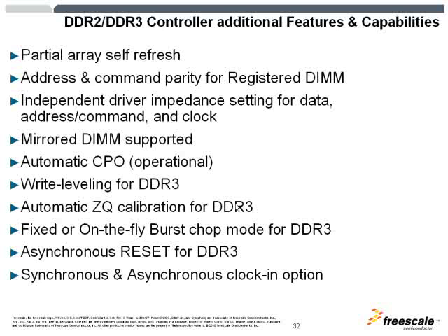Fixed or on-the-fly burst chop modes for DDR3 are available. We touched on this briefly, and as you know, DDR3 operates only in 8-bit burst. With this, you let the memory controller decide either to send 4 or 8 bursts, and that's the on-the-fly burst chop mode, or you can select a fixed burst chop mode where you would select a 4-bit burst chop or a fixed 8 bursts in DDR3.